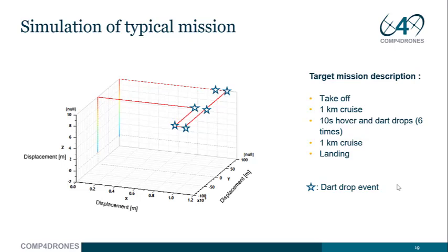The inputs provided to the drone for the simulation are its positions, so namely the altitude, longitudinal and lateral position, and the yaw. The controllers that we have seen before modulate the rotational speed of the propellers to control the attitude in terms of pitch and roll of the drone in order to orientate the thrust vector so that these positions are followed.